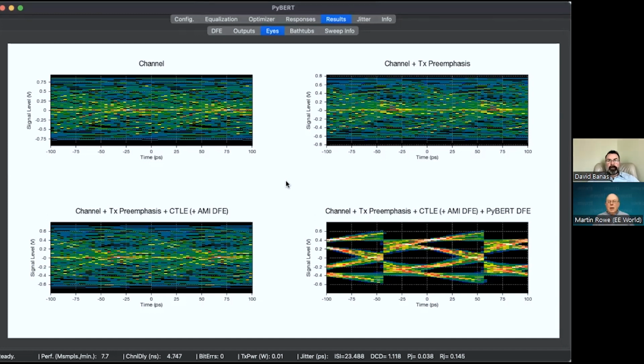That's exactly right. And what you also get from one bit to another is the timing is not perfect. Even though there is probably a pretty stable clock keeping things together, nevertheless, it has what's called jitter: very, very small differences in time from one bit to the other. When does it go high? When does it go low? How long does it stay high or low? All of those affect the opening of the eye.